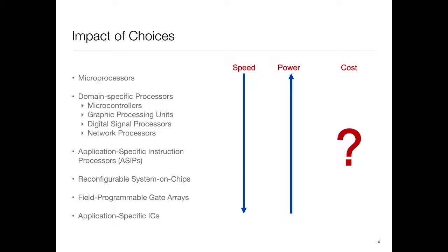But on the other hand, let's say I'm the US Army and I'm going to be creating something which every soldier will carry. Now my volumes are much higher, or maybe Apple, and I'm going to design something and make 100 million of those things. Now I can afford to be out here because the non-recurring cost gets amortized. So the economics of this depends a lot on the volume that you are after.